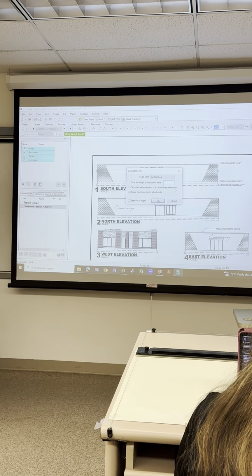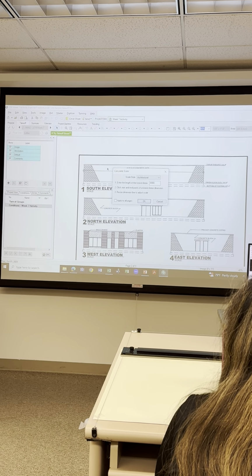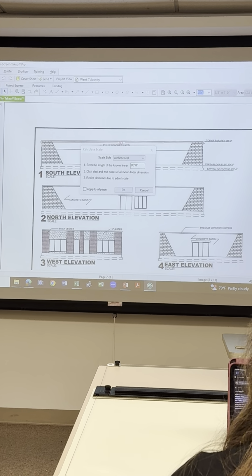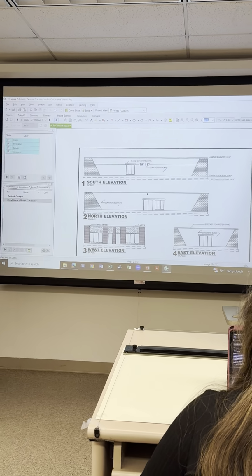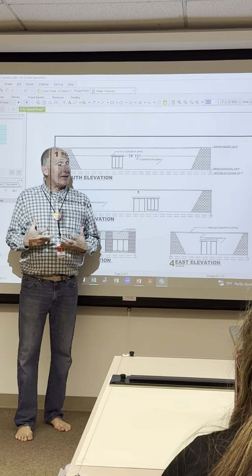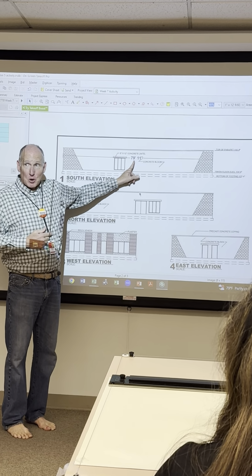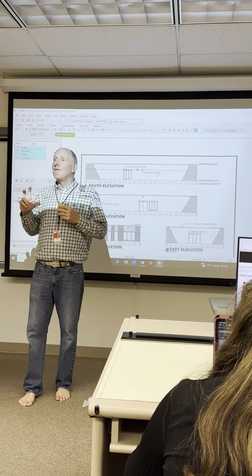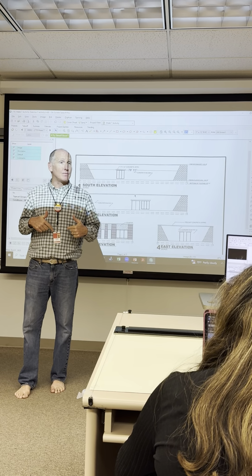We know that the south and north elevation is an overall 80 feet because we interpreted that from the floor plan, and it's from here to there. And we click OK. And look what happened. This drawing recalibrated its scale. It's now showing I'm within an inch. Pretty cool? So the message here: check, verify the scale on every drawing.